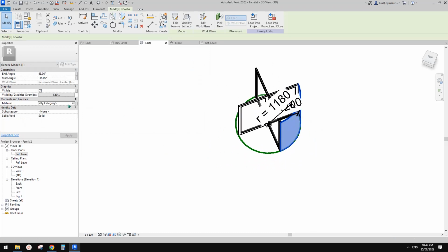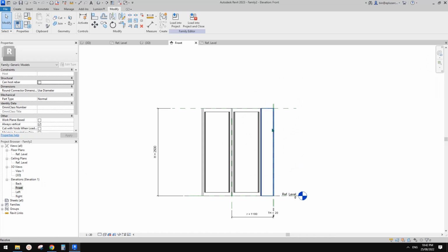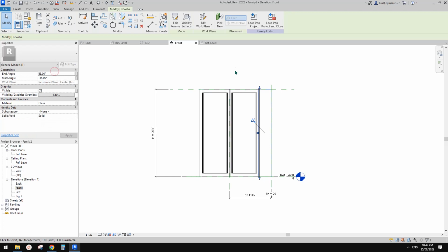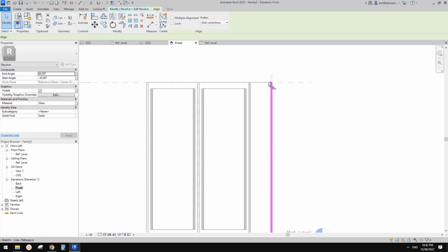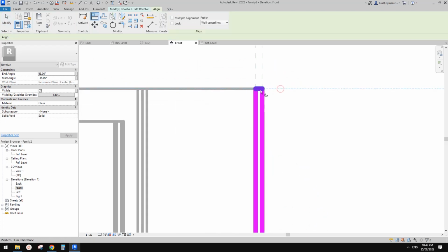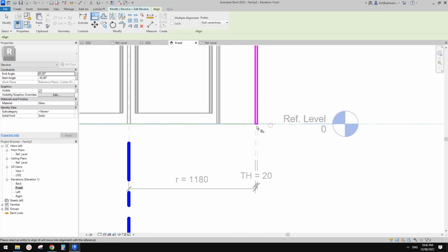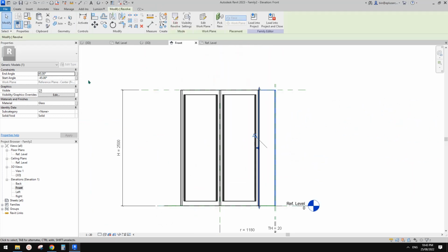This one of the panel. Maybe I'll just make it glass so we can see through it. And so if we need another one, it's basically just copy it. Okay, and then paste in the same place and edit revolve. So you need to lock, because when you copy and paste, you will lose all the constraints. Okay, so you just need to lock them onto the exactly same reference planes and finish. So this time we just need to change this one.